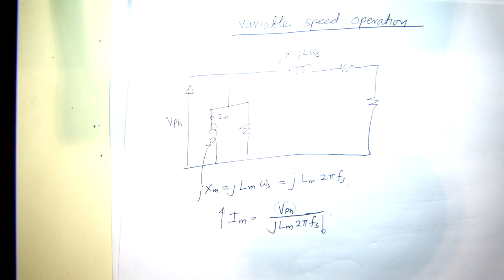So that's not good for the induction machine. If you increase the magnetizing current, it tends to go into saturation region, so it's not designed to operate at that condition. Although in these graphs we saw that the peak torque point increases, at some point you won't be able to operate the machine because it's saturated. So we like to keep this magnetizing current constant when you change frequency.